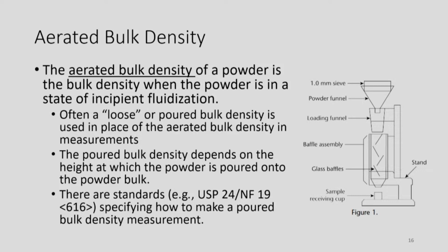Bulk density, you might know, depends on the height from which it flows down, right? If it's too high, then there will be chances of fluidization and you might lose some powder. But if the height is too low, then there will still be some agglomerates that contain some bonding between the particles that affects the volume calculation.